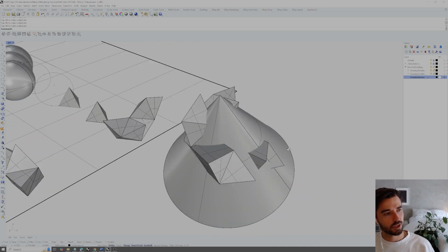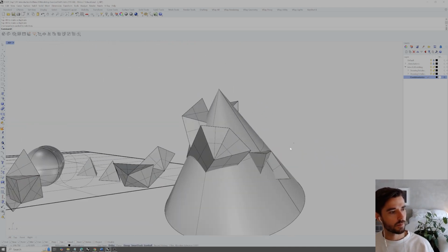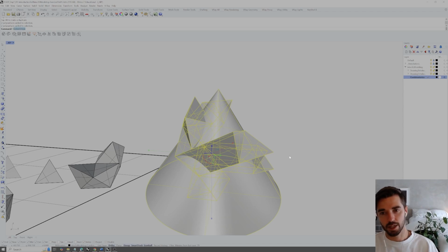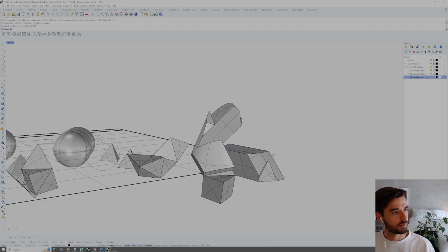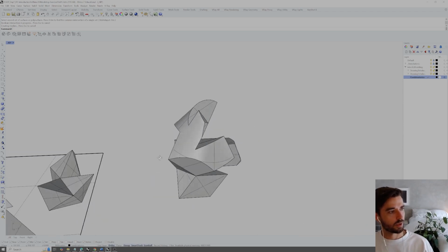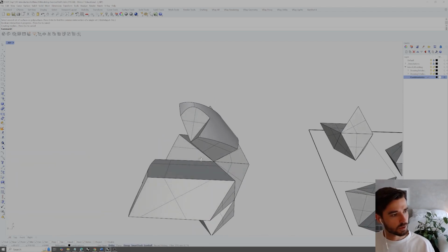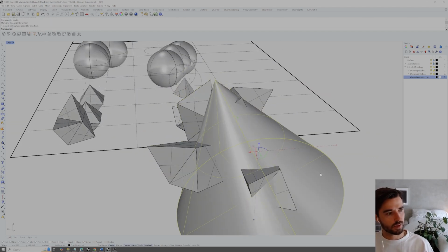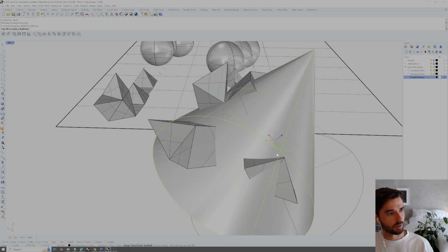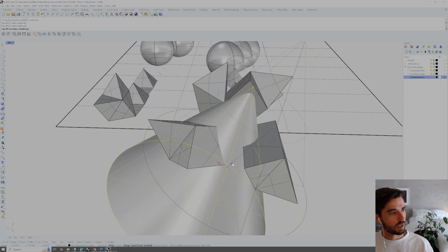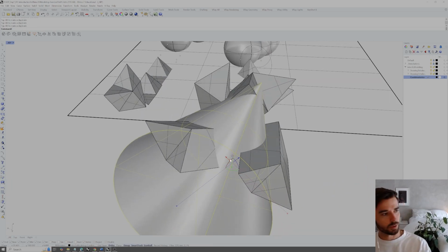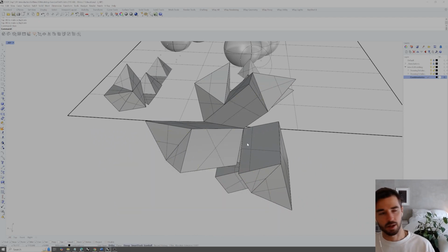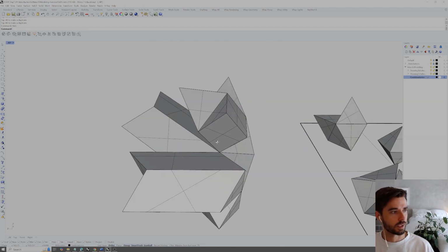So with it in that position, I'm going to select both solid geometries and type Boolean intersection, enter, delete input, yes, enter, and now we have the output of that Boolean intersection. So you can see we're still missing quite a bit of mass. We've now totally severed certain portions. So I don't think that particular placement is going to work very well. What we might actually want to do even before the cone, so I'm going to just hide this cone, and we can re-show that and then use it in a moment.